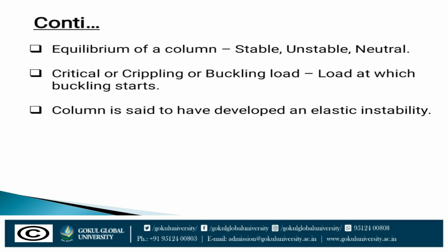Equilibrium of a column has three stages: stable, unstable, and neutral. Critical, crippling, or buckling load: the load at which buckling starts is called the buckling load. The column is said to have developed an elastic instability.